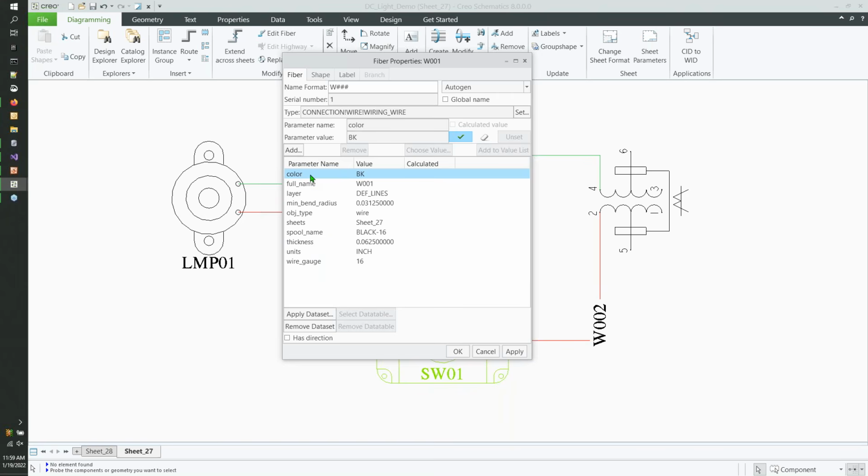At least for the pretty stuff on the parametric side. If we want to have colors transposed from schematic to populate pretty colors on the parametric side automatically, we have to have a convention where the naming of the color here for the conductor on the schematic matches a color that exists in the user's color palette that is doing the parametric cabling operation.